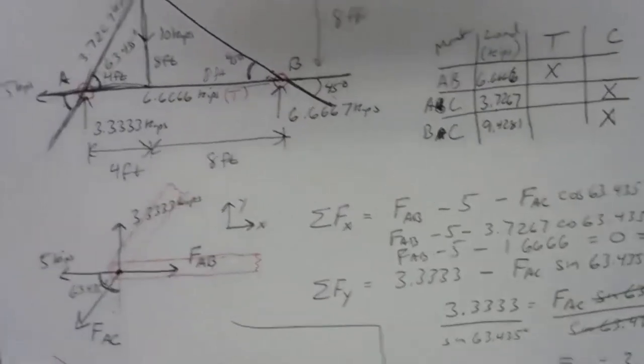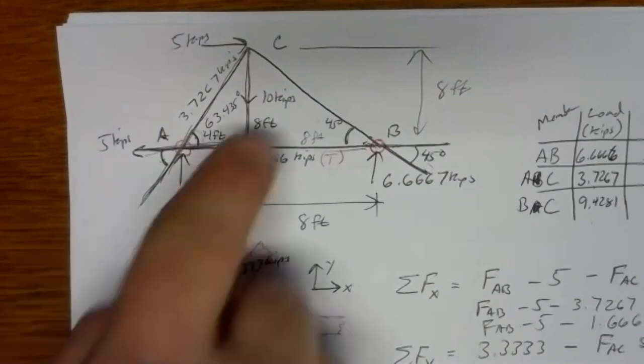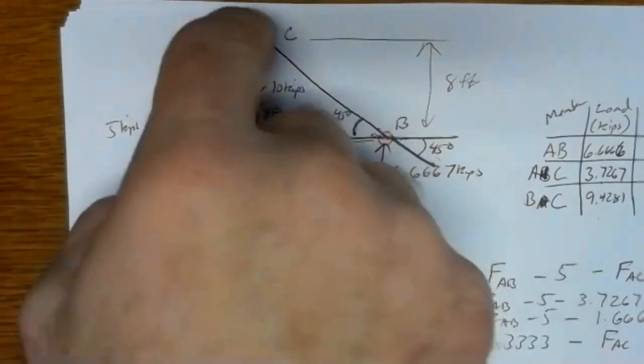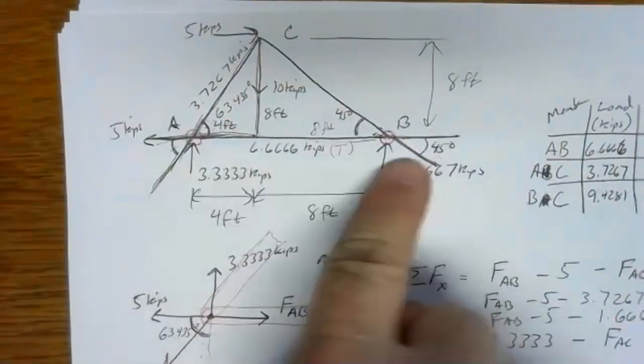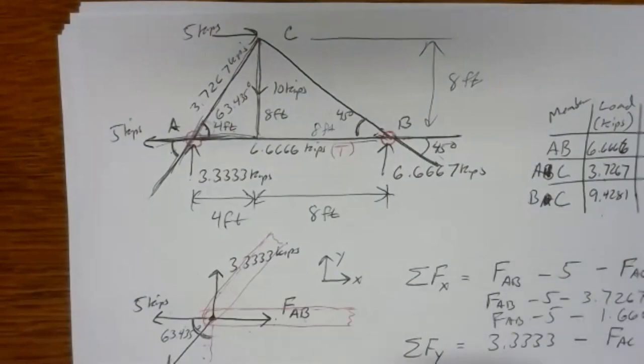Now with simple trusses, you can kind of see that from the loading. Here we're pulling down. Use your imagination a little bit and try to think about how this would look if it starts to fail. You know, kind of play that video. A lot of people in this field have a pretty good intuition about these things. Imagine what would happen if that, instead of 10 kips, was 100 kips or 1,000 kips, and the structure starts to fail. How is it going to fail? Well, if you pull down really, really hard on that, these two members are going to want to buckle. They're going to want to kick off to the sides. This member down here is going to try to stretch out. You can visualize tension or compression.